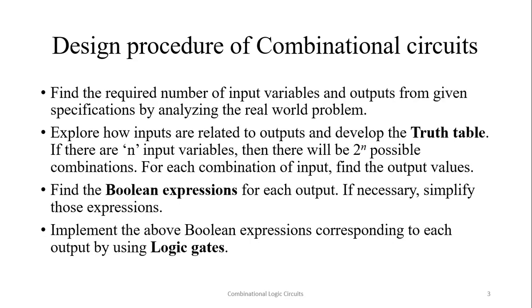Design procedure of combinational circuits. Combinational circuits are used to implement real world problems in digital circuits. So what is the procedure? The first step: find the required number of input variables and outputs.